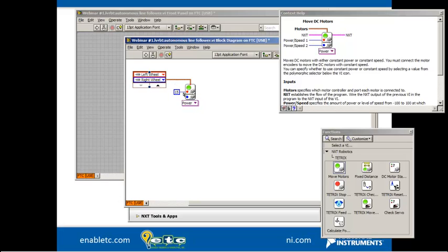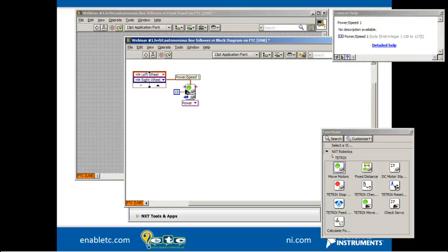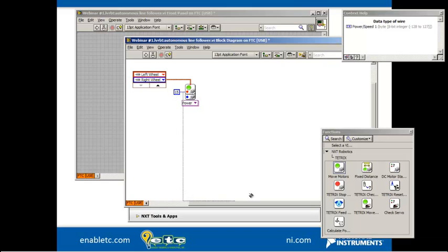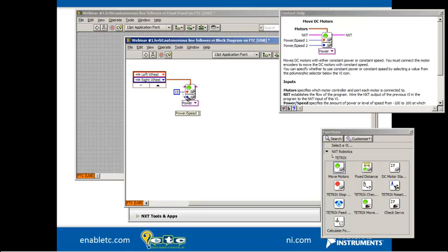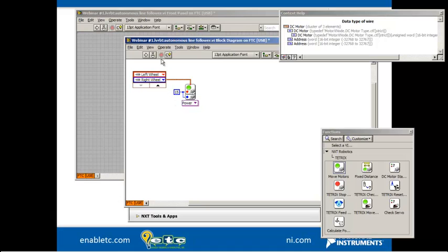Well, notice when I hover over any of these lines that are connecting our constant values to our function block, it turns into what appears to be a spool of wire. Well, that's exactly correct. The idea of connecting inputs, outputs, and functions within LabVIEW is called wiring. So whenever I want to wire, I click once on my starting point, and then when I move my mouse around, I can define where I want the second point to be. In this case, I'm going to click on the second bottom input, and now we've wired up 15 to both of them. So this process is called wiring, and you can do it by clicking on a terminal or on another wire.